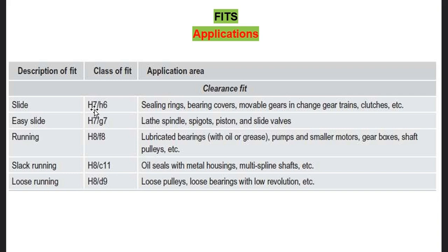This 0.2 value is arrived at by using the different fundamental deviations and different IT grades that we use. IT grades are like IT1, IT2, 3, 4 up to 16, 17, 18. Fundamental deviations are from capital A to capital Z, small a to small z. So like I said, capital letters will represent the hole, and small letters will represent the shaft.